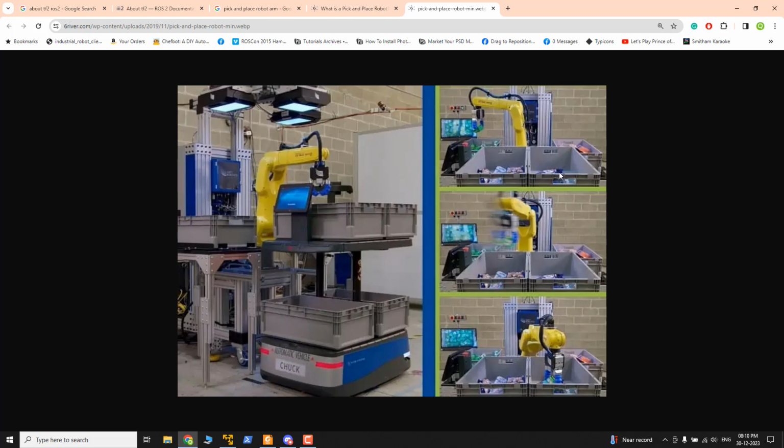That's where the transformation comes in, because if you know the transformation matrix, or simply if you know the relationship between the camera pose and the end effector pose, then you can compute the robot coordinate of the object if you get the coordinate from the camera. If you get the camera coordinate, you can convert it into a robot coordinate using the transformation.